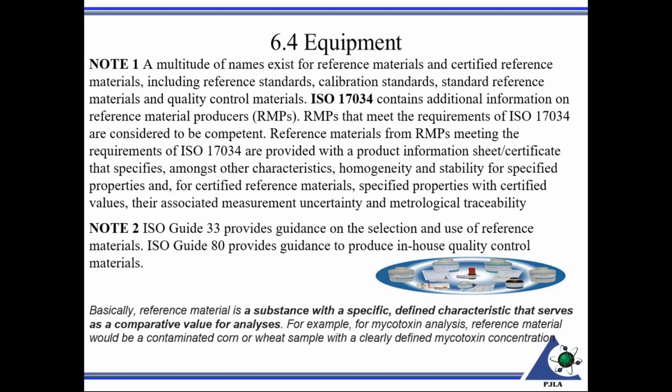Folks that are doing calibration, I see reference materials utilized a lot for pH and conductivity, those solutions that have a known content in them, usually like 7.0 pH, already produced by, ideally, a 17034 reference material producer. Those would be other examples of reference materials.